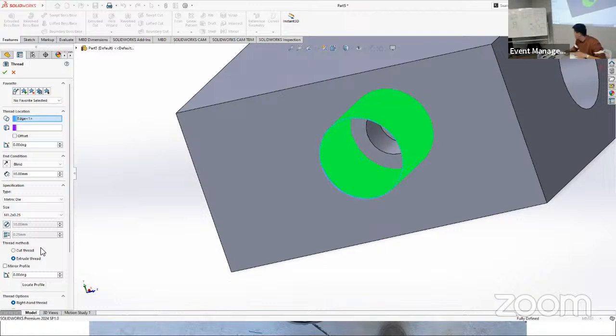And we're going to extrude that thread because, okay, let's explain that too. So when you have a thread on your bolt, it's something like that, right? And on the sides, you can see these teeth. And by default, if it's M10 scale, it means that it's 10 millimeters of diameter from the outside of these teeth. So if we're going to make a thread on that plane, it should be overlapping here. So by making it extruded, we're creating that thread, and it's going to work very well with our bolt.